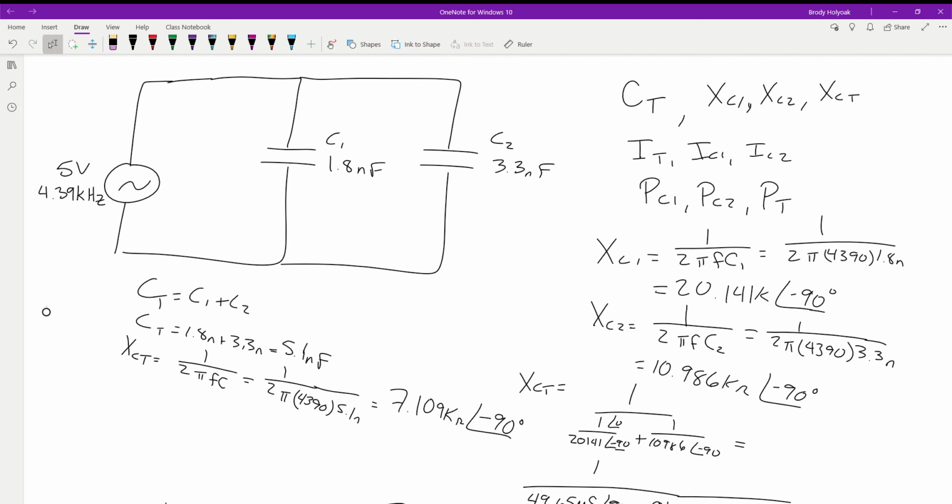Yeah, at the very beginning if you want to. That's just fine. If you're having to solve for powers, which you should always solve for power, especially in resistors, make sure you have a large enough resistor to handle it. You can convert this to whatever you want, just as long as you indicate what it is. In some of the labs, people like using peak to peak. That's fine. Some people like using RMS. I pretty much use peak because it's real quick and easy to get those values. You don't have to calculate anything.